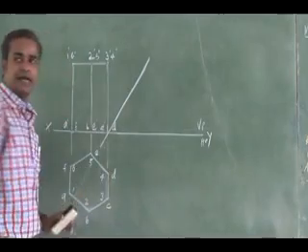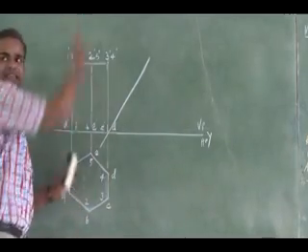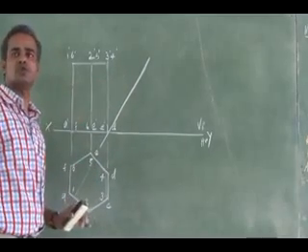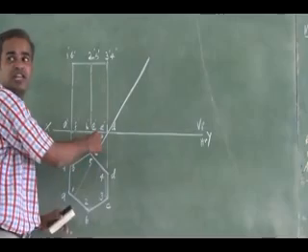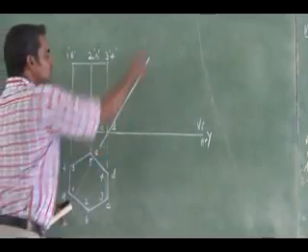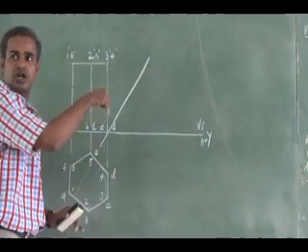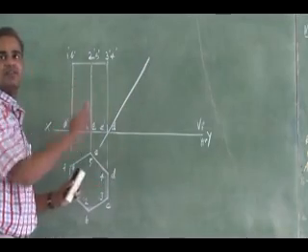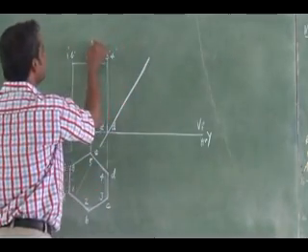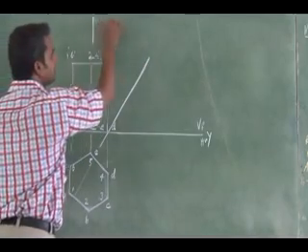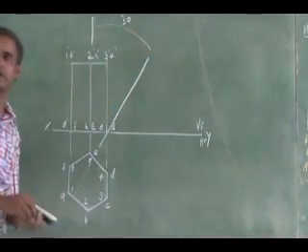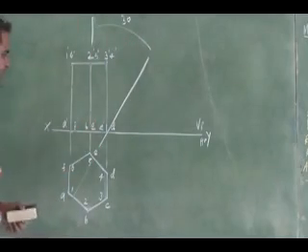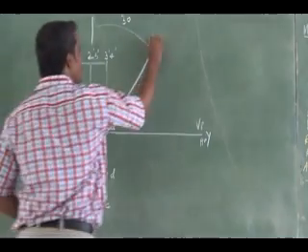So to what angle do I have to draw it? To the axis, this reference line has to be 30 degree and the conditions also should be maintained. Which is going to be resting? CD is going to rest on the ground. So this is the reference line. CD has to rest on the reference line. So my reference line has to touch CD and I have to change the reference line orientation 30 degree incline to the axis. Right. This is how I can keep it. Now, this is the axis. For this axis, this reference line is 30 degree incline. So this is my x, y.